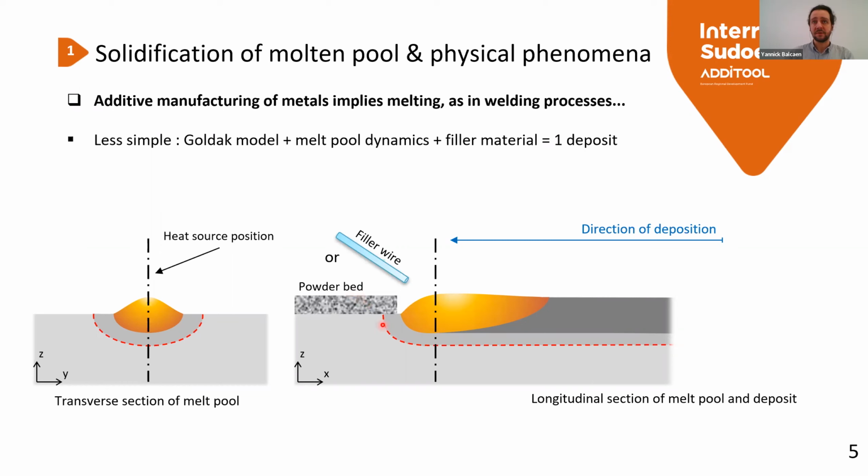We have a remelting front that is at first not important, but we have a solidification front, which is hard to understand and governs microstructural formation, but also not only on the solidification front, but also in the heat affected zone.